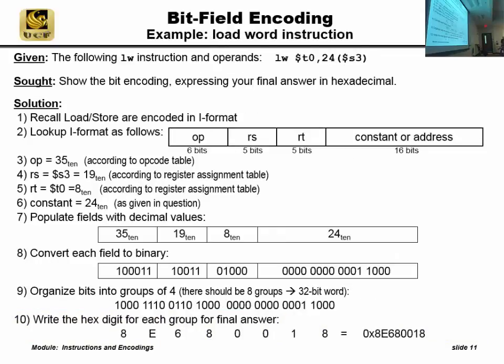Let's try another example. We had one more encoding, which is the load word. Actually, load is an immediate mode encoding. Remember this offset of 24? That's going to be encoded here. Opcode for LW is 35. It's in the table. You notice when we have op, you don't have a func. Func and op work together. We'll see more examples. We can look up this value.